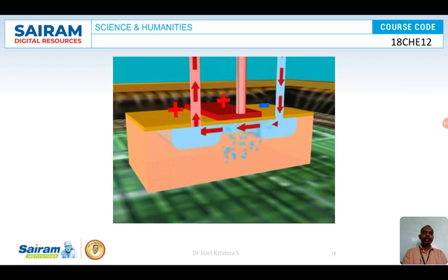I think you've now seen how n-type is obtained and how p-type is obtained. Surely we'll tell you n-type is rich in electrons, p-type is rich in holes, right? I think now you would have better understood why n-type is called so. When we dope phosphorus, silicon becomes electron rich. When we dope boron, it becomes rich in holes, right? So this is how your silicon is manufactured and PV cells are manufactured.